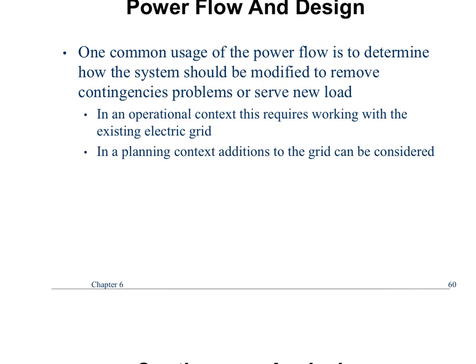So why do we spend so much time on load flow? Because the system, again, has to be stable for n-1 contingencies. And one of the stability things is no lines are overloaded and no voltages are out of whack. So what ISO New England does constantly is they're always running these contingencies in the background, saying take this strongest source out of service and then see what happens. And then perhaps take the second strongest one out of service and see what happens. Because you have to be able to handle that loss of the biggest contingency, and you have 30 minutes to get the system back to a happy point.